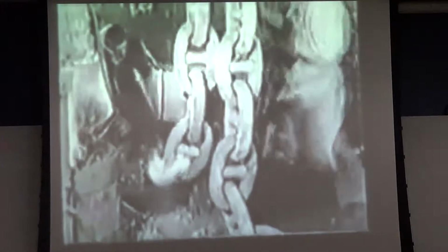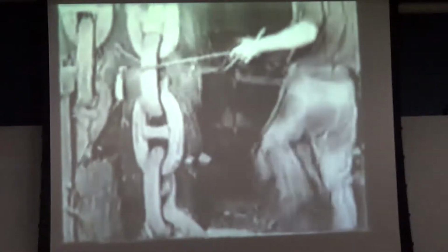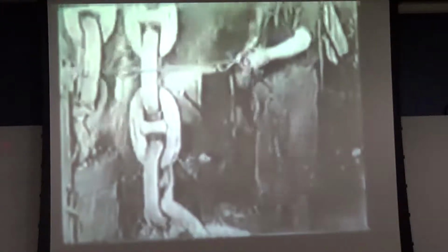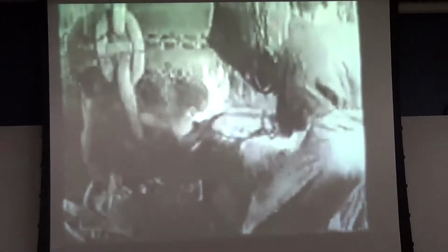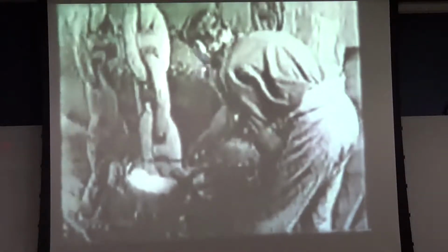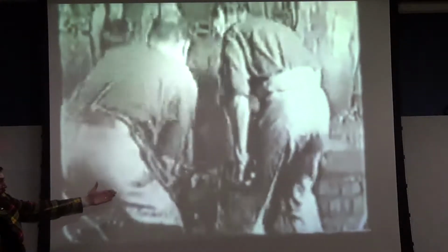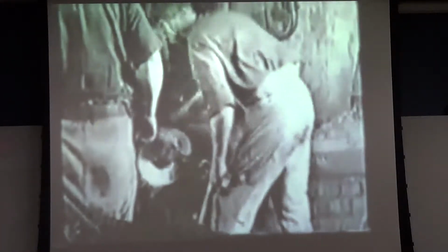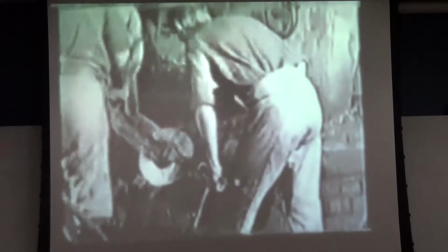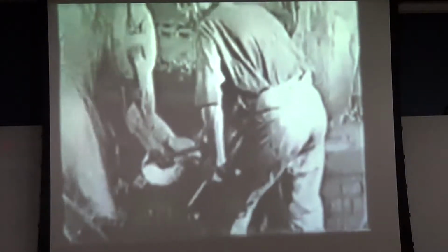Really? They are holding on to the same hammer. It's a large hammer that has two handles coming out of it to allow for two men to swing at the same time. I've even seen pictures of some hammers that were so large they had three handles for this type of work. This tool is called a swage, and they've got a lower swage underneath. They're contoured to support the round cross-section. They don't want to mar that because that would become a weak point in the surface. So they use shape tooling to accomplish this.